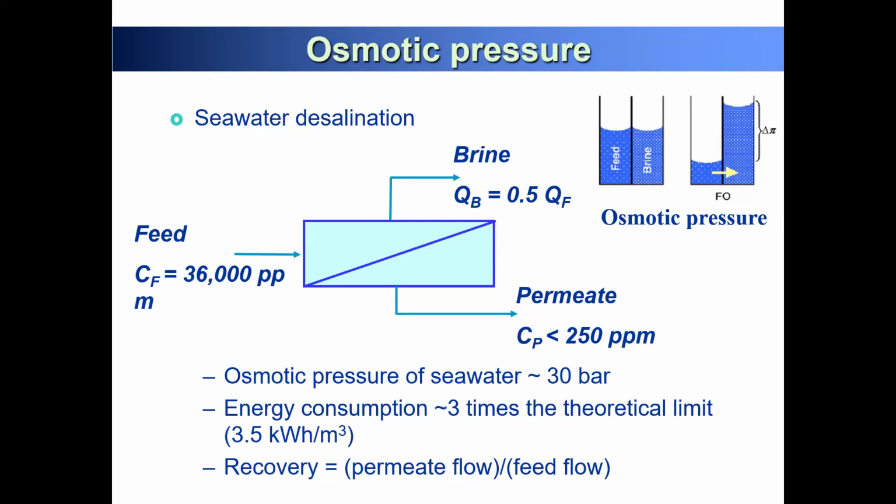We have lithium, magnesium, calcium, silica, and any other component; you have to calculate each concentration, R, temperature, and the dissociated solutes individually, and then get the osmotic pressure. So it's very difficult to look at all the details. So we just make a rough calculation from total dissolved solids.